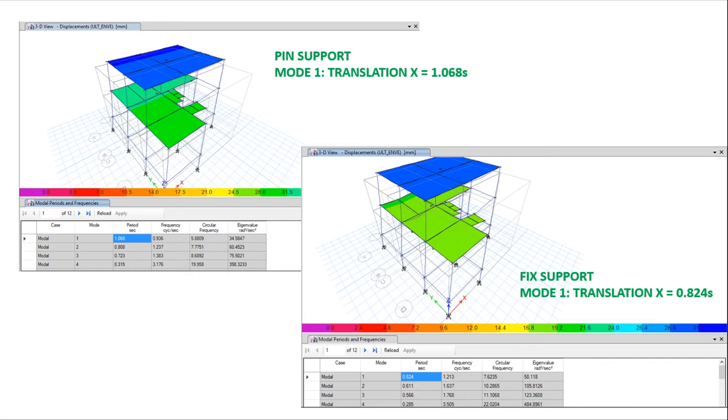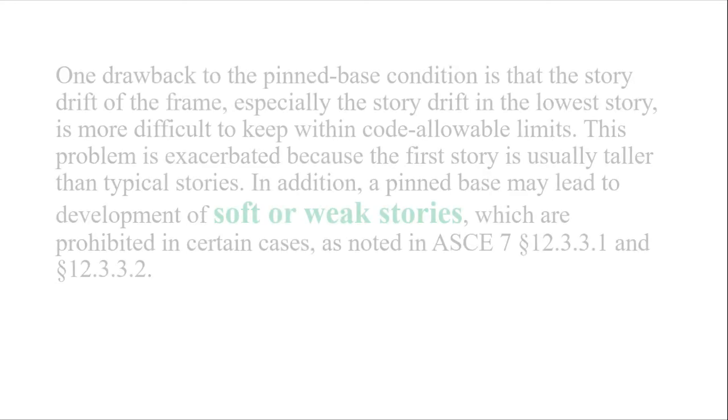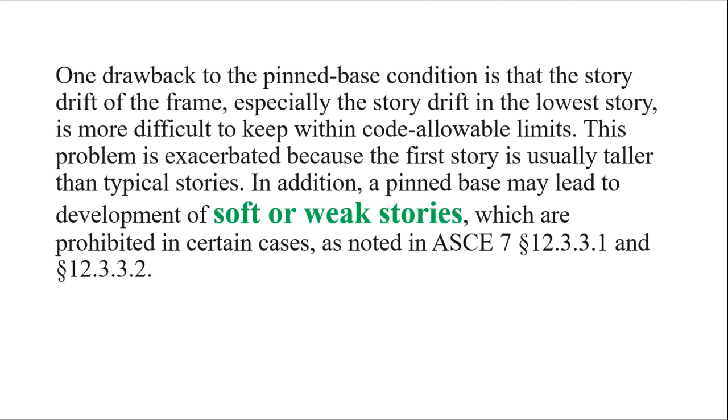Okay. One drawback naman to the pin base condition is that the story drift of the frame, especially the story drift in the lowest story, is more difficult to keep within the code allowable limit. Kasi napansin natin na mas malaki daw pala ang story drift talaga kapag pin supported. Okay? In addition, a pin base may lead to a development of a soft or a weak story.